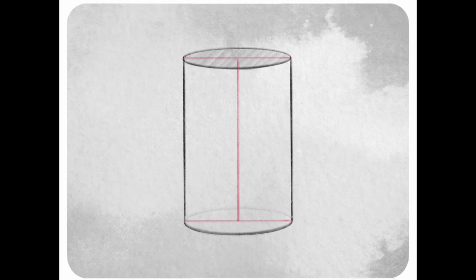It's really easy to want to change that angle and adjust it, but if you think of the central part of a cylinder as being like a capital letter I, all the angles within that structure inside on the red lines, you can see those are all right angles, nothing's turned or tweaked. That holds true no matter how you turn the cylinder, and that's a really important thing to understand when we go to draw cylinders. You can see every one of those would be marked as a right angle.